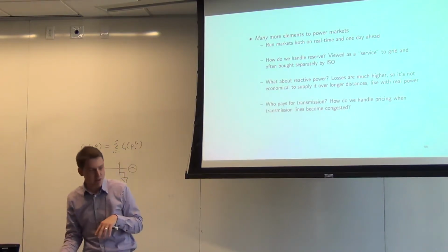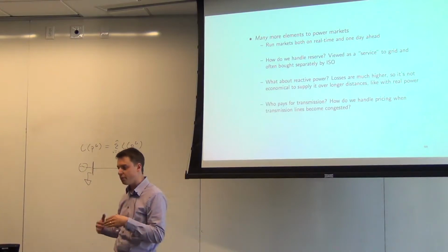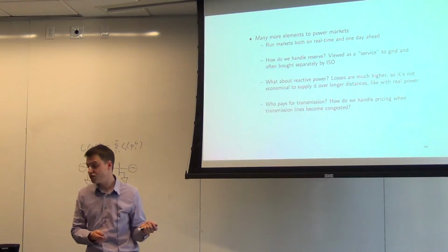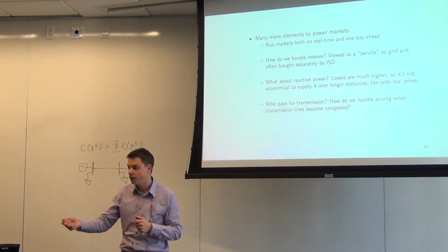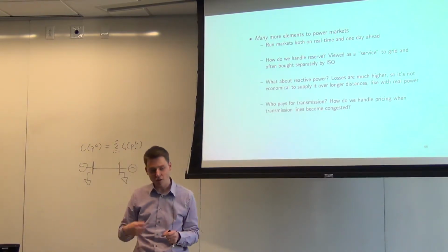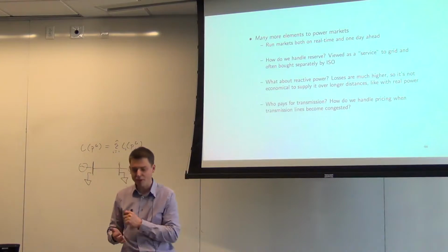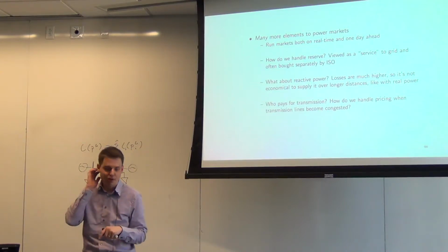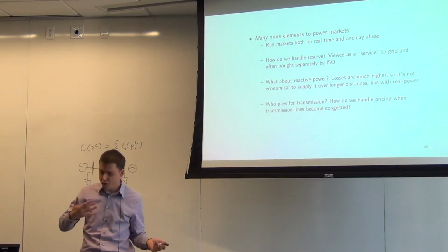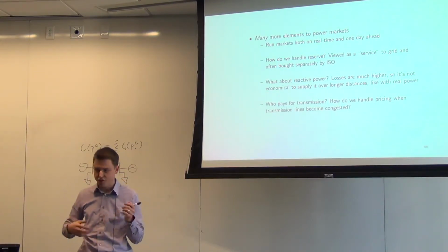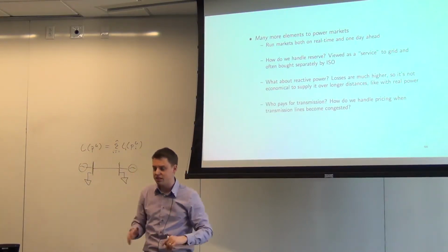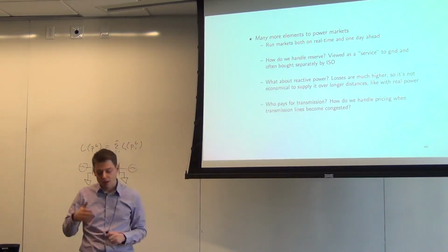And this is a very different process, right? Because the generators that can bid and offer to give power 5 minutes from now might be very different from the ones that could bid to give power a day from now. For example, big coal plants and things like this typically take a lot more time to start up. Certainly nuclear takes a very long time to start up. And so they might not really be able to change their generation that much within the 5-minute time span, but they could plan a day ahead, versus other things like fast gas turbines, which can actually spin up very quickly, and so maybe they're going to want to bid in the real-time market because it's a little bit easier for them that way and they have an advantage that way.